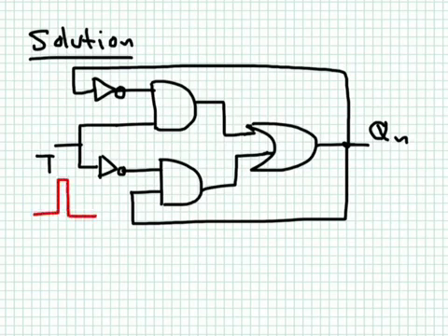It can be edge triggered, either positive edge triggered or negative edge triggered, so that by the time the delay happens in all these gates and the output is changing, the input will already disappear and there is no toggling signal anymore. It returns to its no change condition, and then the circuit can proceed.